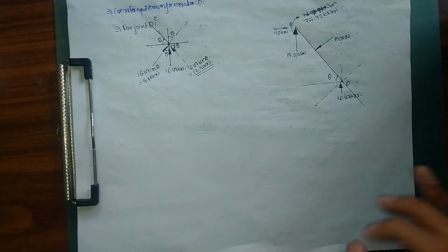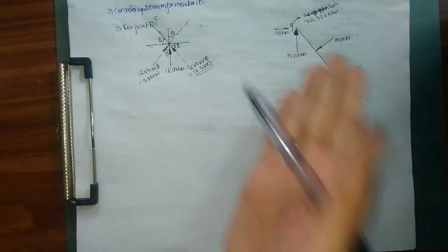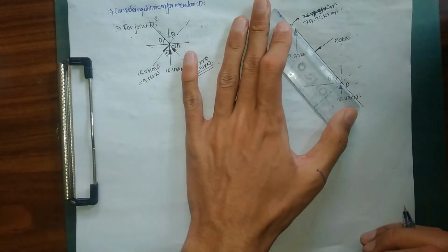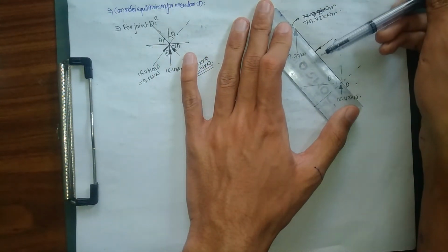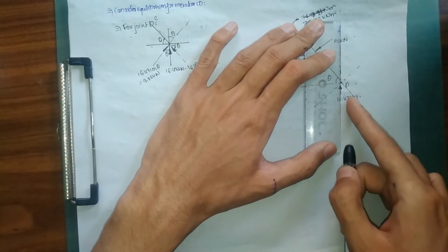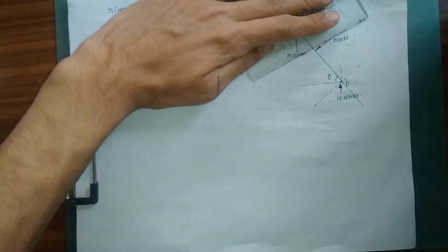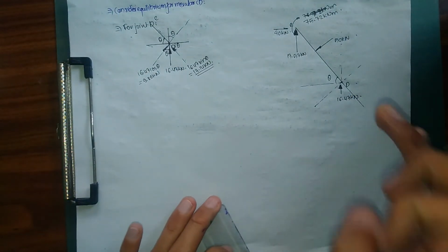As I already explained before, shear forces are those forces which act perpendicular to our member CD. Since member CD is inclined, our shear force must also be inclined in a certain direction. So this 16.43 is not going to produce shear force, because it is acting vertically upward. It must be resolved at an angle theta in order to produce our shear force.